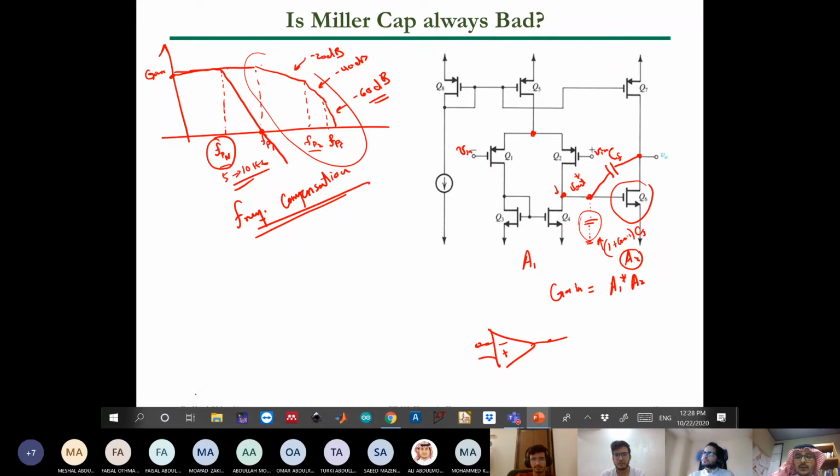Good. Let me ask you before leaving this topic, what do you think of this circuit here? What does this circuit do? If this is Vn, what will be your V out? It's a buffer. It is a buffer, so V out will be Vn, right? And your effective output impedance will be the small impedance seen from here, which is usually almost close to 0. Okay, so this is a buffer.